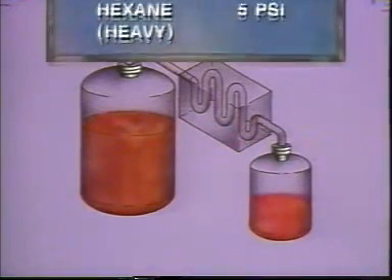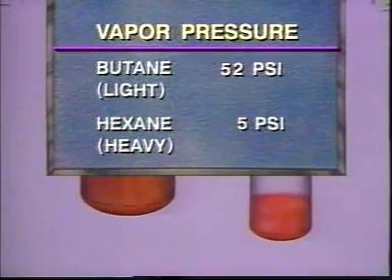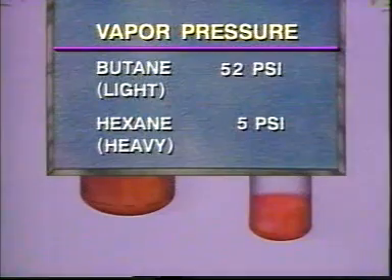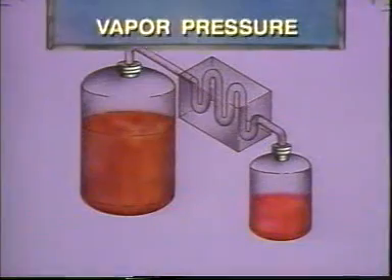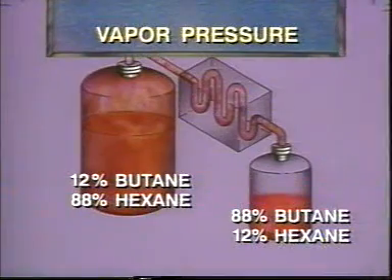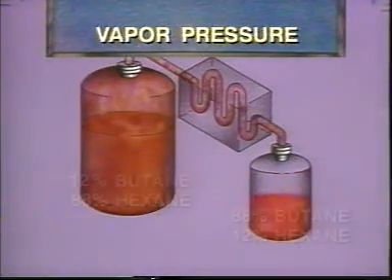In the distillation process, we are concerned with the boiling points of a mixture of components and not a relatively pure substance like water. And each component in the mixture exerts a different amount of vapor pressure inside a closed vessel. For example, at any given temperature, a light hydrocarbon like butane will have a higher vapor pressure than a heavier hydrocarbon like hexane. This is because less heat energy is required to move the light molecules into a vapor state. Since butane has a higher vapor pressure than hexane, the butane boils out at a lower temperature. This explains why we can separate butane from hexane by heating the mixture and then condensing the vapors.